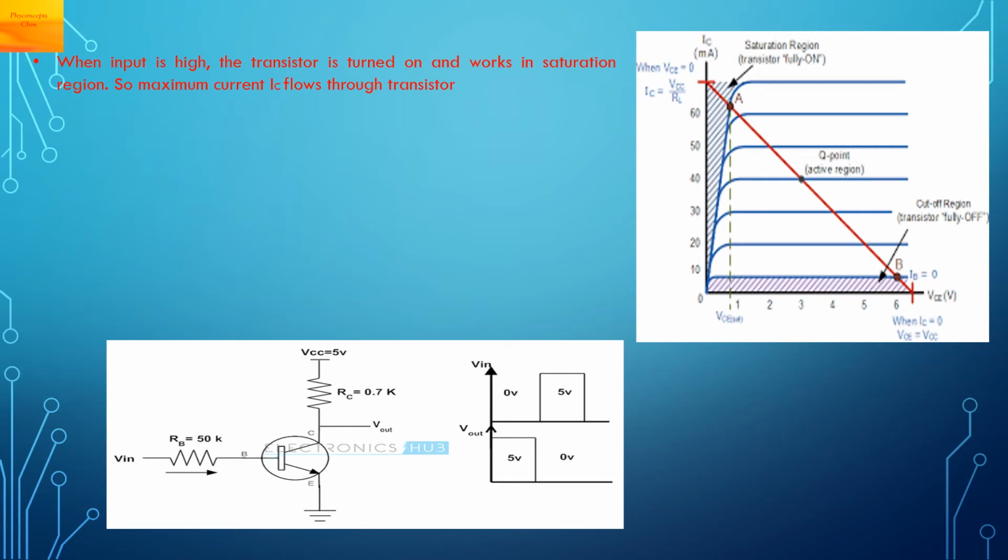When the input voltage is high, the transistor is turned on as we saw, and it works in the saturation region. So maximum current IC will flow through the transistor. When the input is very low, the transistor remains in the cutoff region, so the current IC is 0.